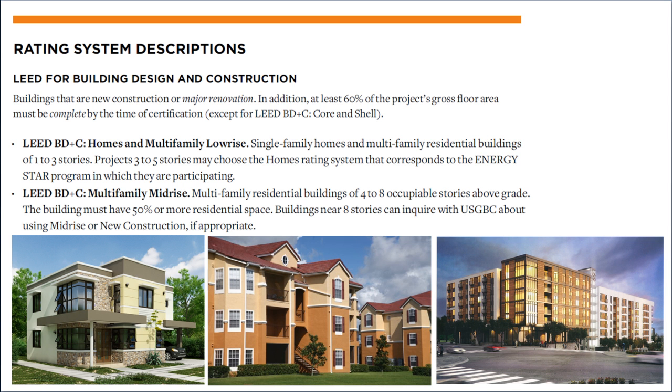LEED BD+C Multifamily Mid-rise. Multifamily residential buildings of 4 to 8 occupiable stories above grade. The buildings must have 50% or more residential space. Buildings near 8 stories can inquire with USGBC about using Mid-rise or New Construction if appropriate.